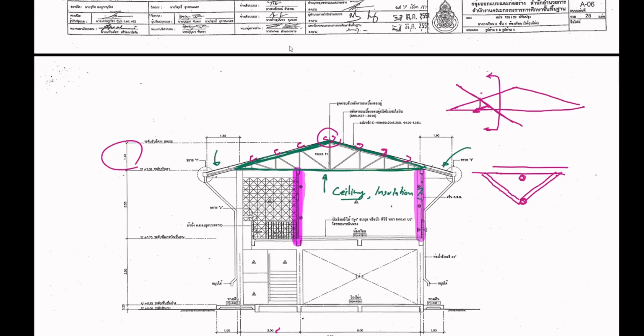For the roof system, we need to consider the weight of the truss right now. The weight of the truss. Now you're talking. What kind of load is the weight? Material dead load. Is it a point load or uniform load or anything? So the weight of the member is a point load? Distributed. Yeah, it's a distributed load.